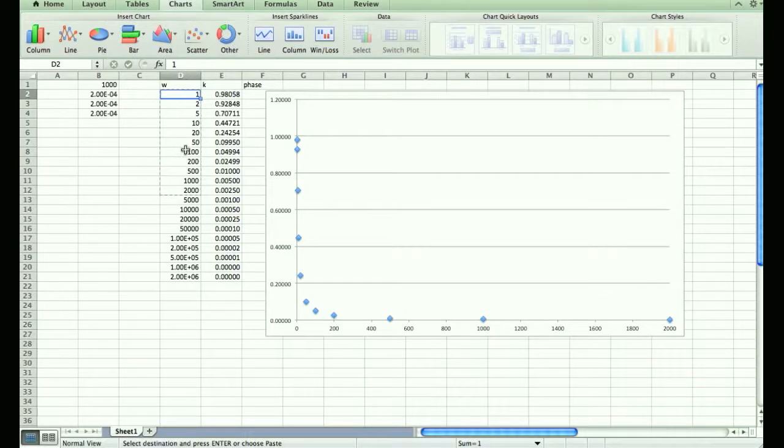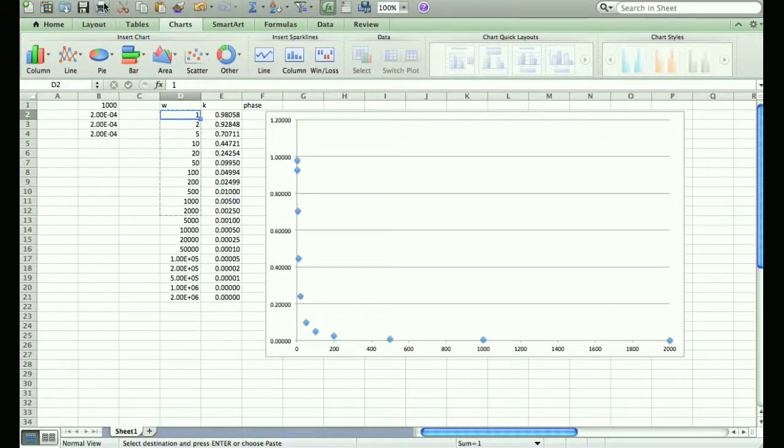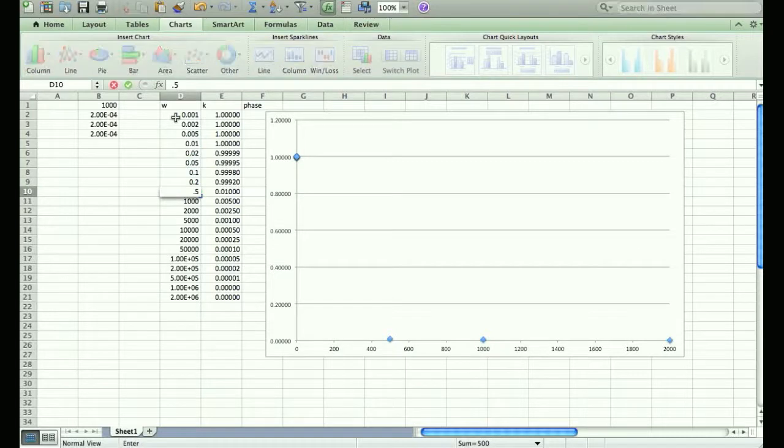And you know, we could do this process of zooming in a little more, but I think you can agree with me that the way I'm doing this leaves a little bit to be desired, because no matter how I try to zoom in on the plot, I can either get a nice look at the low frequencies and no look at the high frequencies, or vice versa. It's very hard to capture the details of what's going on at the low frequencies and the high frequencies at the same time, just because the scales are so different, right? If I want to see what's going on between 0 and 2 radians per second, my plot has to ignore what's going on up at the millions of radians per second.